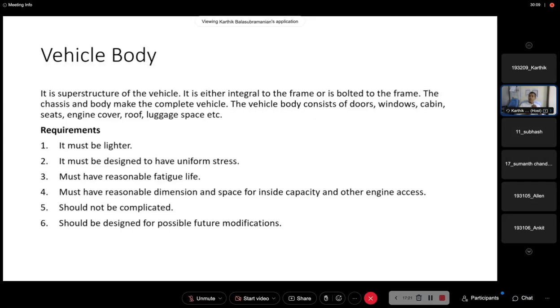You can do so many things. You can increase the stiffness of the vehicle frame. You further increase the stiffness of the vehicle frame so that it becomes even stiffer compared to the vehicle body. Or you add flexible mountings between the vehicle body and the frame so that any relative movement is absorbed by the flexible mountings, right? Those things can be done. Or you try to better integrate the vehicle body and the frame by a lot of rivets or bolts or complete welding techniques.